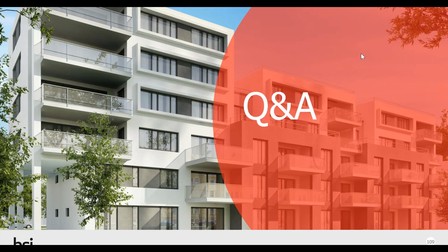I think there's a need for a test standard for fire spread across balconies, in particular in respect of laminated glass, because none of the tests available at the moment, 8414, etc., are really relevant to fire spread via a balcony. So I think there's a need to understand how fire progresses across balconies and to qualify the threat to life and property. I don't think there's an absolute answer to that one yet, and I think it will all be borne out in the course of time.